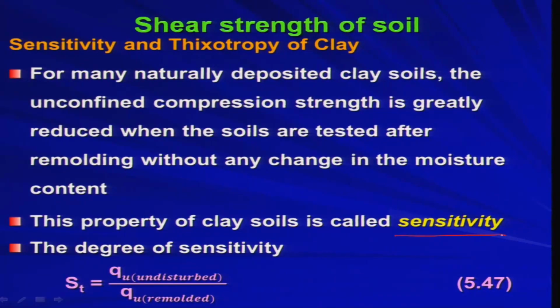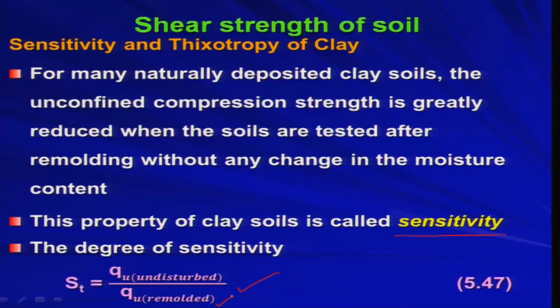Now we are going to quantify this sensitivity. The degree of sensitivity is given by St is equal to qu undisturbed, that is whatever is actually available in the field or in situ condition, divided by qu remolded, which you get from the laboratory experiment. How will you get qu undisturbed?